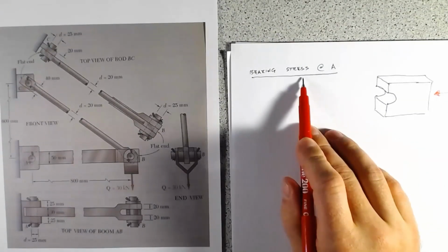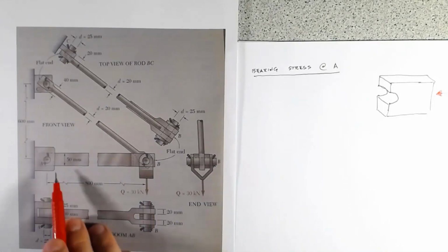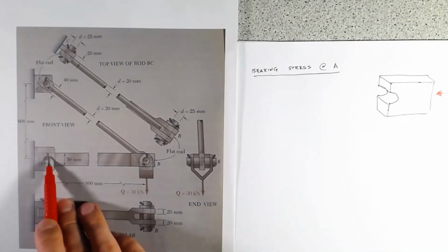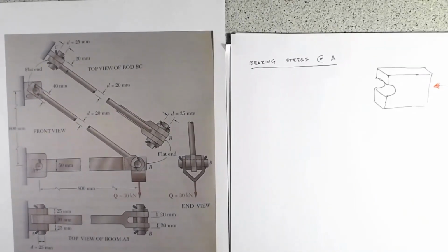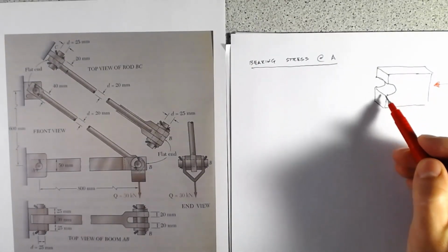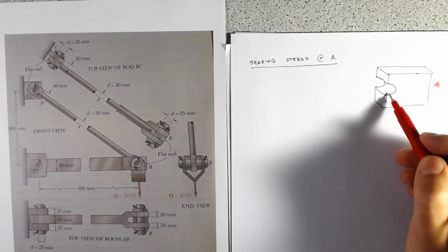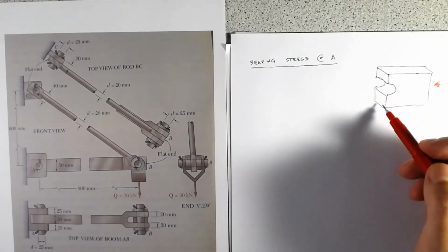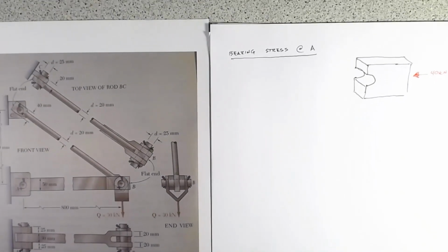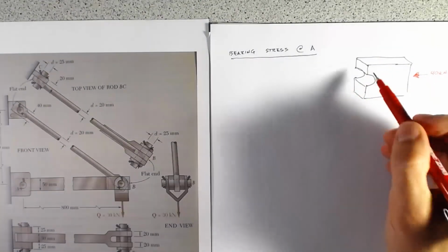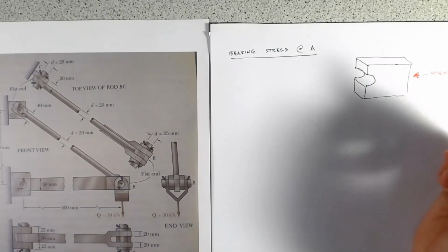And what we're looking at with this bearing is how we're transferring from this beam onto this pin. So what we know is our force, now the key is trying to find our area. Well, for our bearing, it's only bearing within this hole. So the area top and bottom isn't contributing towards being able to get this load into the pin. It all has to occur where there's a pin.